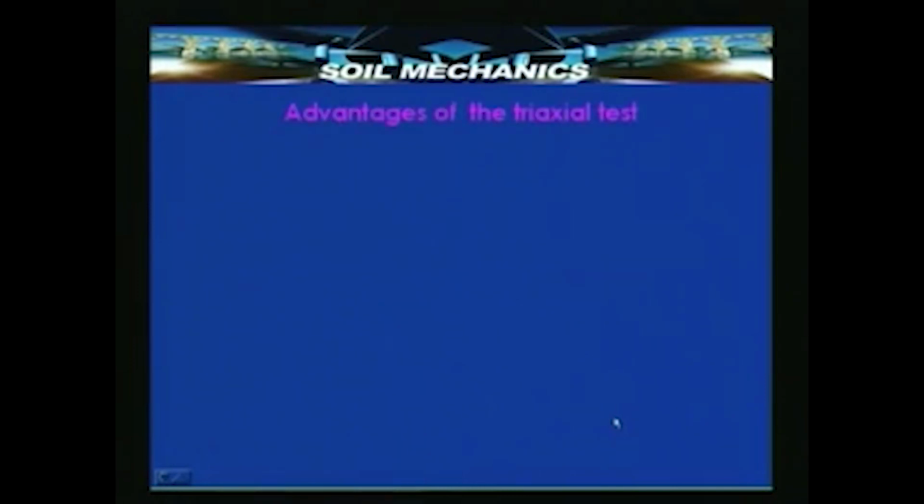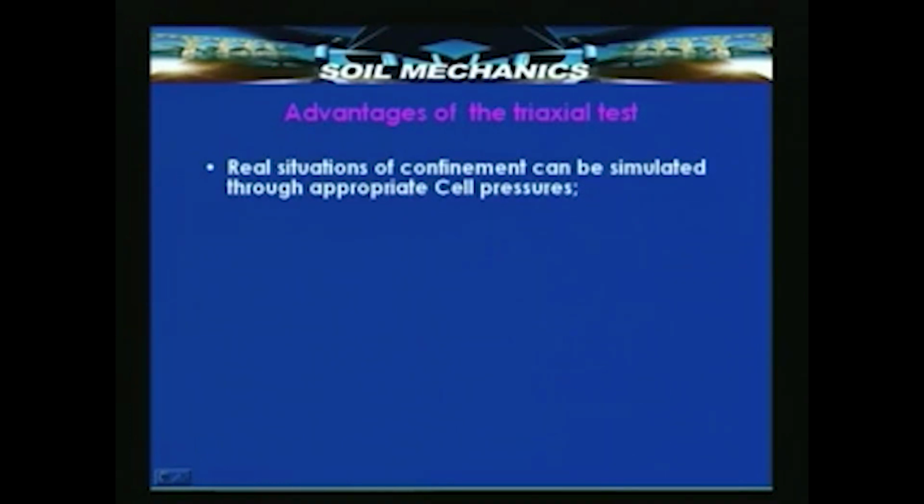Now, why do we need to conduct this triaxial test? Why do we need to understand the importance of these triaxial tests? It is because there are several advantages associated with the triaxial test compared to the direct shear test. The advantages are: 1, real situations of confinement in the field can be simulated. As I mentioned a few slides ago, a soil is under a certain confining stress at a given depth in nature, in the field.